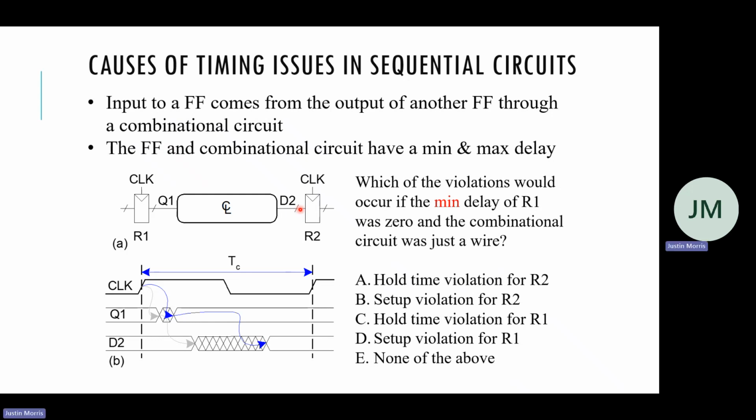It didn't violate setup time. Then when the latch here is trying to disable, if there's no delay from here to here, the next input is immediately trying to change what this first latch is trying to latch onto. That's how it can skip the input.